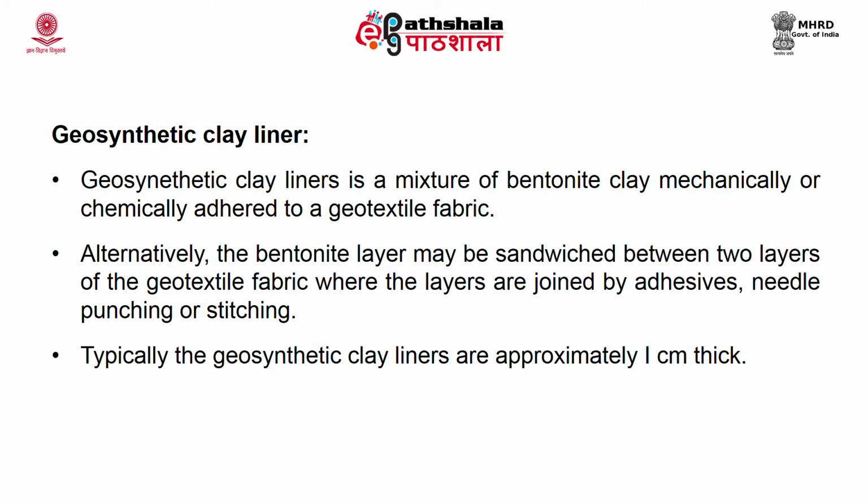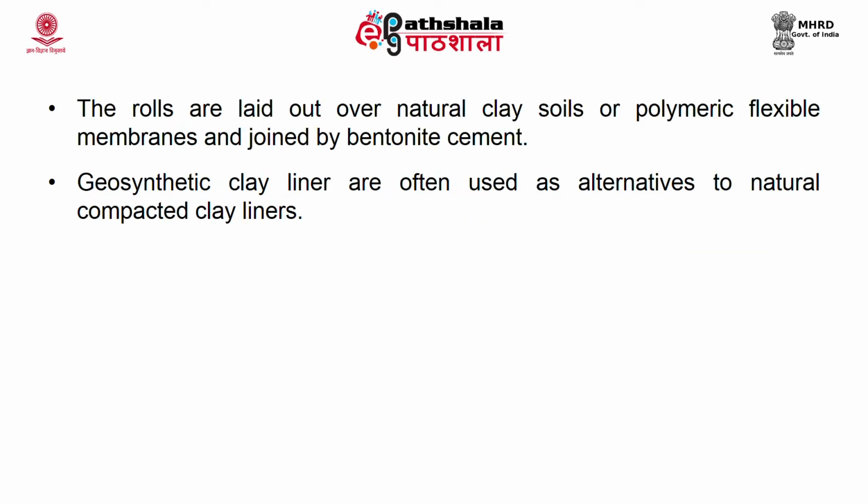The typical geosynthetic clay liners can be approximately 1 centimeter thick. When this geosynthetic clay liner is laid over a natural liner, for example, any clay material or bentonite enhanced soil, it can be fused to the natural liner by using an adhesive, namely bentonite cement.